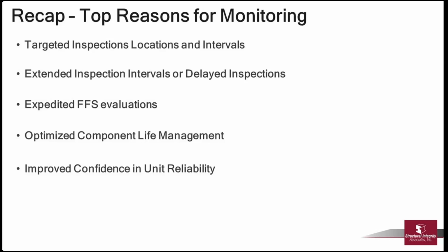The limitation on those is temperature right now. If it's below 800 degrees, we can accurately monitor real-time thickness data. Once you get above 800, the challenge with the spray-on transducers is an oxidation layer forms that often adds additional noise to your signal.